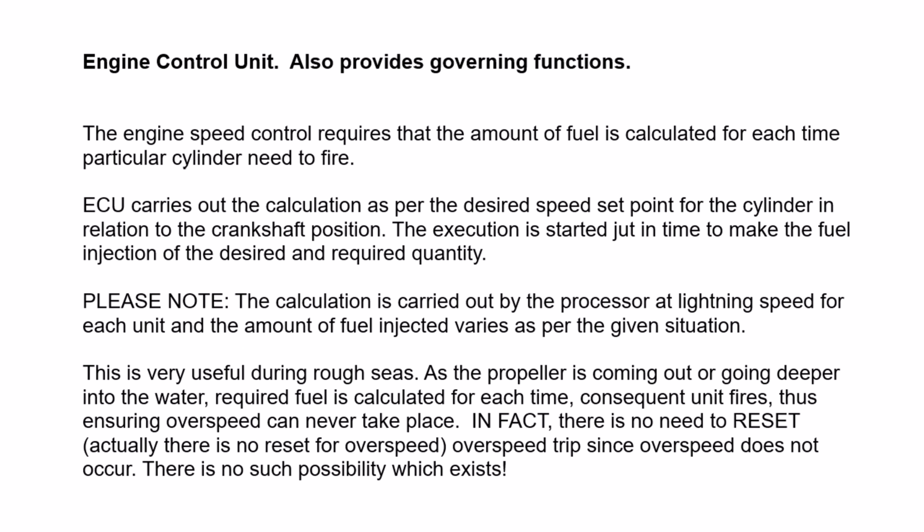Now, the ECU, engine control unit, also provides the governing function. The engine speed control requires that the amount of fuel is calculated each time a particular cylinder needs to fire. For every firing, the amount of fuel is recalculated, but it doesn't take time.